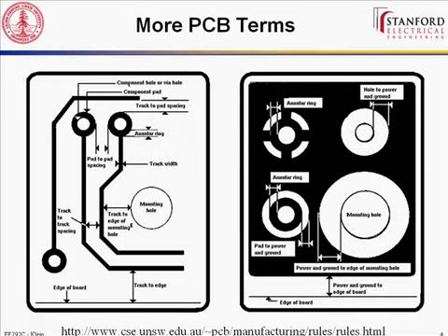So if you look at your development boards, the LCD, the keypad, the battery backup, and the power connector are all through-hole components. So they have holes, and the only difference really between a hole and a via is what it's used for. But mechanically it's basically the same thing, except vias are usually very small. So you generally are not soldering things into vias. They are handy to have for debugging, though.